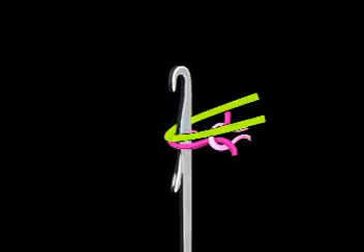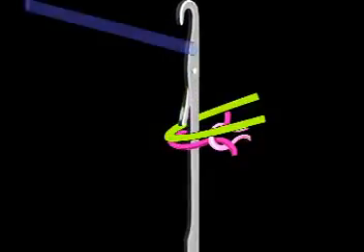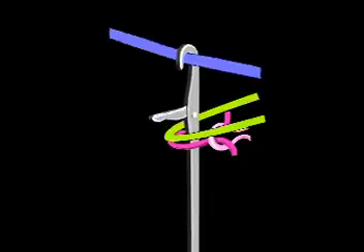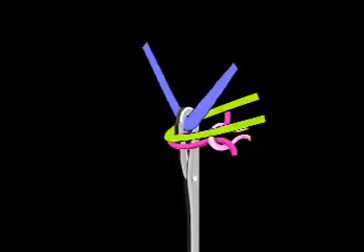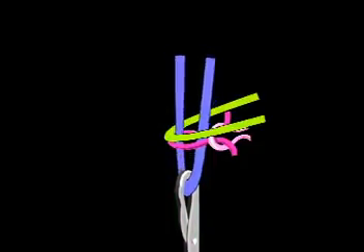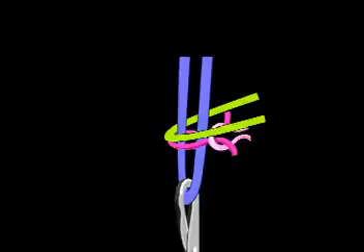The knit cycle occurs with the next feed of yarn. At this time, both yarns are cleared. A new yarn is fed and pulled through both the held and tuck loops, forming a tuck stitch. The stress caused by holding one elongated stitch for an extra course causes more length shrinkage, but less in width than a regular knitted stitch. The tuck loop makes the fabric wider and thicker and slightly less extensible.